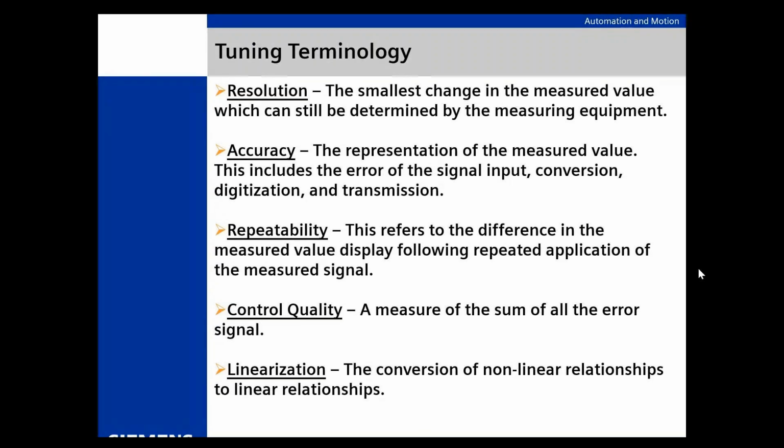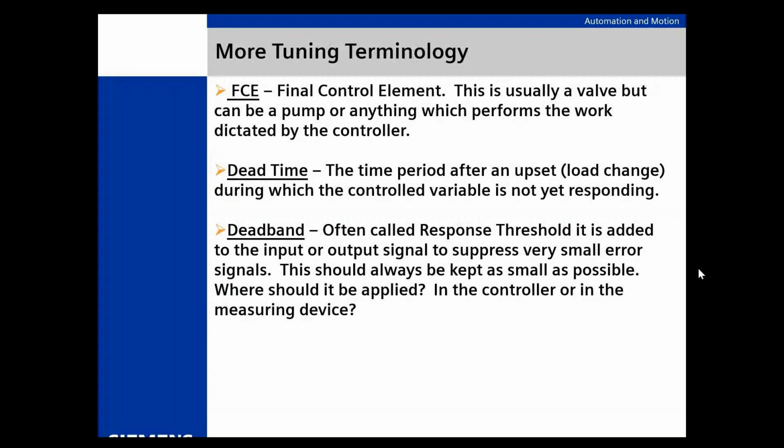Okay? Now, the final control element, that's generally a valve. Pump maybe, but generally a valve. That's what does the work. Okay? If it's not sized correctly, I've said it before, I'll say it again, you're not tuning that loop.